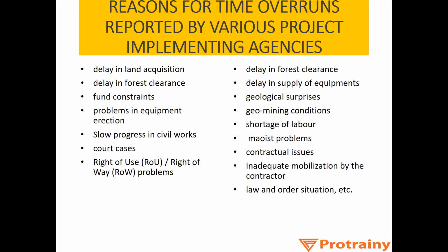We considered that when we excavate for any XYZ project, there will be only soft soil, and we accordingly provided the BOQ. The contractor also quoted a lower rate, considering that it is soft soil and easy to excavate. But when they started excavating, after 2-3 meters the soil was very hard, with hard boulders and rocks. In that case, the contractor will not be able to perform in that time, nor at that cost, not even with the equipment that he thought.